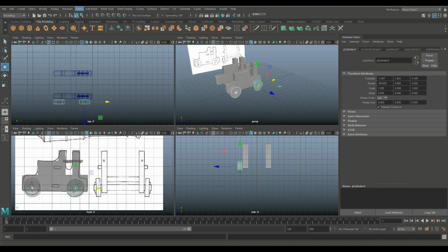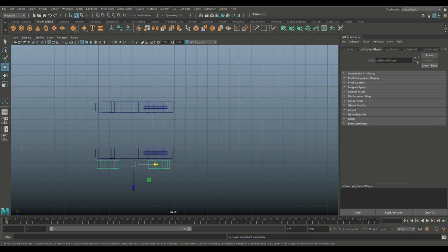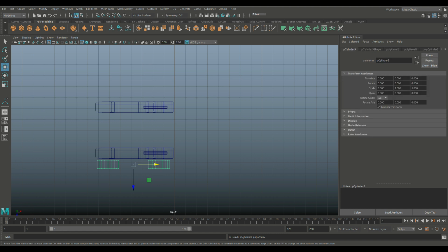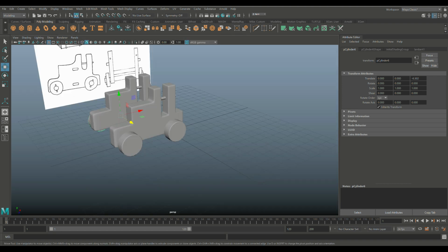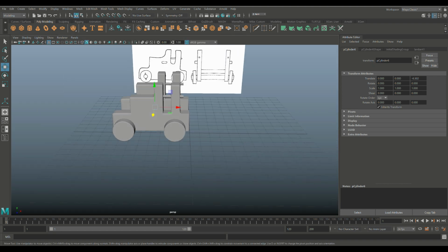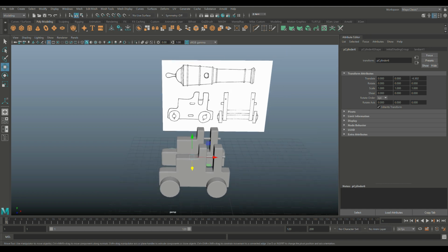Select them both, go to Mesh and Combine, and then we can go in here and let's check where it's positioned. Okay, we're going to Control D to duplicate, W to move. Let's move them over here like that. Give them slightly more spacing. That's good. All right, that's good. And then we need to have that mechanism, that's the axle and the little pegs there.